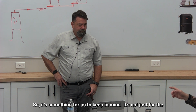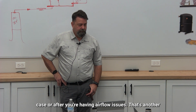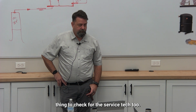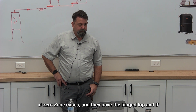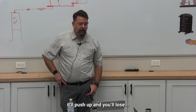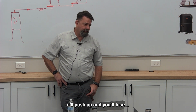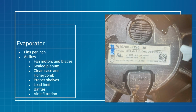Keep in mind, it's not just for the startup guys to be checking that, like after you de-ice a case or if you're having airflow issues, that's another thing to check. If it's wrong, it means you have to fix it. If you don't check it, you can't fix it. I found out that the 1086 has zero zone cases, and they have the hinged top. And if that top is on top of the fan shrouds, when it does ice up, it'll push up and you'll lose all your lift, and then your ice is going to be extreme, so it's exponential.